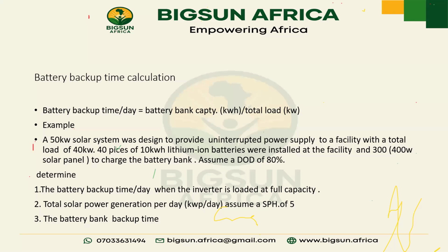That's why I said that when you calculate the total power the person consumes in 24 hours, besides the battery, your goal is to be able to generate the total power that the client is consuming in a day within this 5 hours of PSH or 4.5 hours. In that case, you don't have any flaws in your design. Okay?